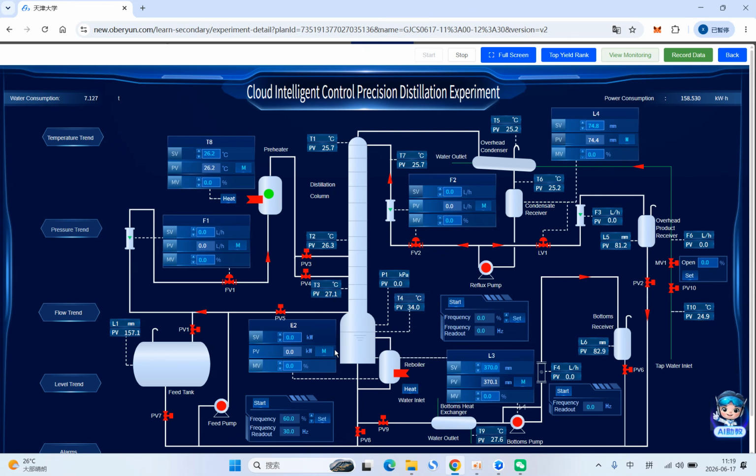However, for this control, for this computation, we only use manual mode. So actually, SV and PV are identical the entire time. So MV is how we open it, how we control it. It may be the degree of the valve opening or the electricity cost for something like the reboiler. What percent? 0% to 100%.